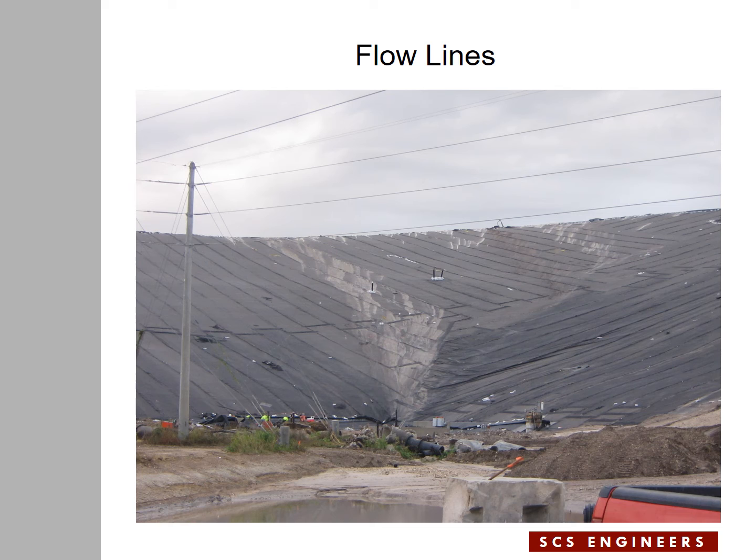The stain clearly shows the flow pattern of water in the concave surface area, in the pie area, and you can see that there's a lot of cross-panel flow in the pie-shaped area. And when it comes to the bottom of the slope within the pie area, there's a concentrated flow reaching the bottom, which is that convergence of the water in the geocomposite.